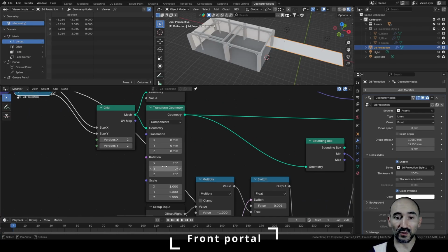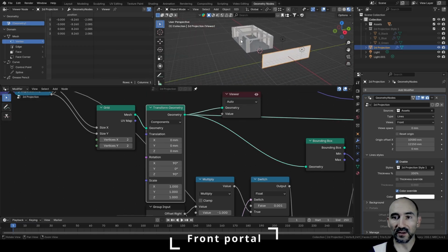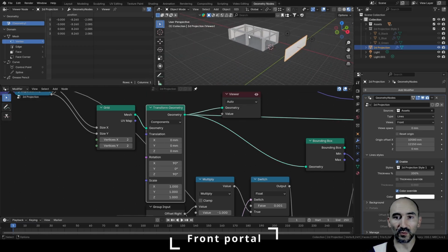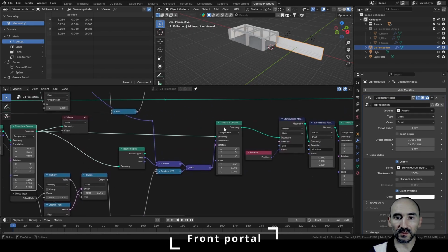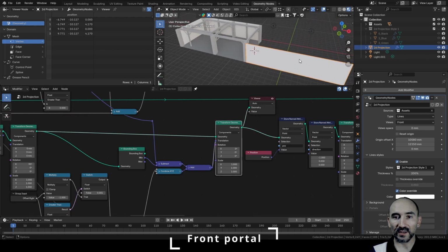Now let's take a look to the rotation. If I press Ctrl Shift here, I have the wrong rotation because I want to maintain the correct rotation for this point of view, and for this reason I can easily reset 0 for the z and leave only the x-axis in 90 degrees.